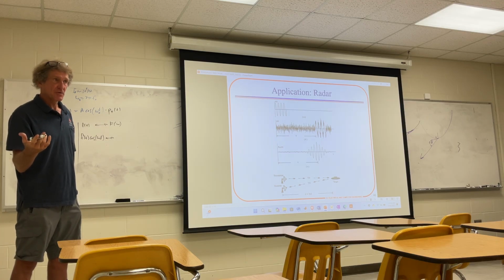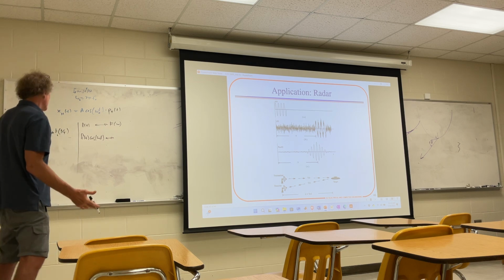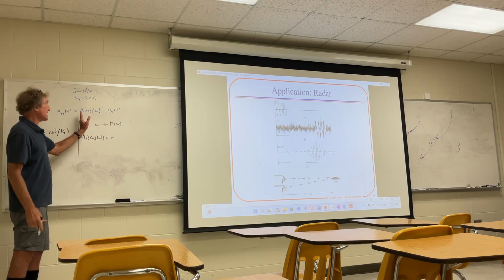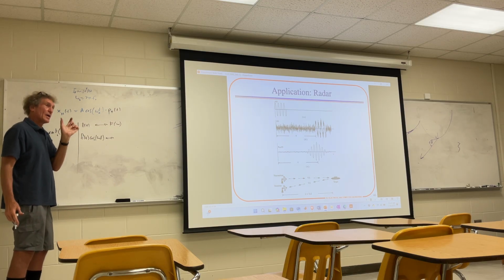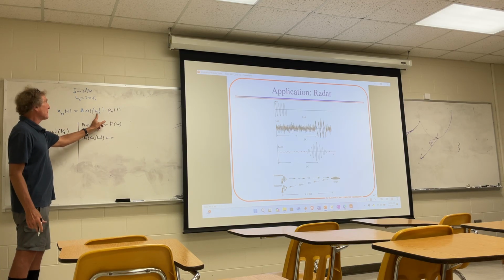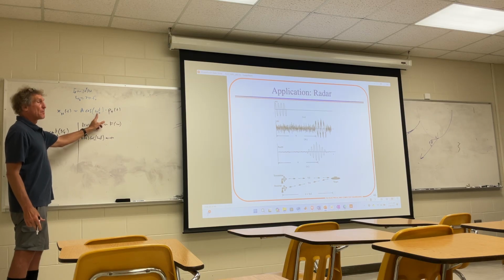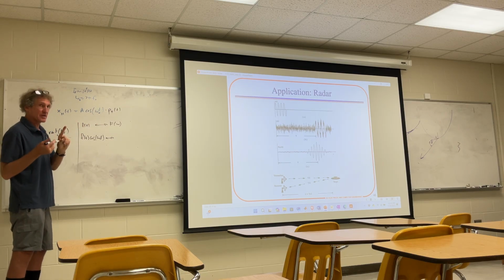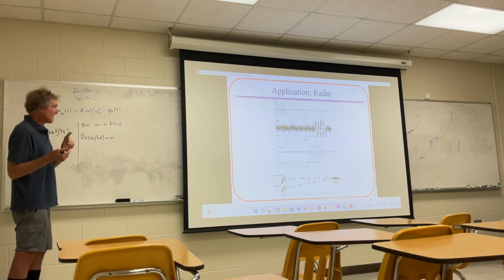There is amplitude and frequency. This is amplitude modulation. If you look, the amplitude of this carrier right here is, quote, modulated. It is only going to have a value of the cosine waveform over a limited width. Otherwise, it's 0, so amplitude modulated. If it was frequency modulated, it would be omega naught plus something times t, and that something is a function of time, so the frequency would actually shift that you're transmitting. Can you all follow me on that?